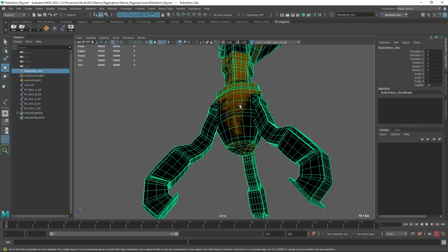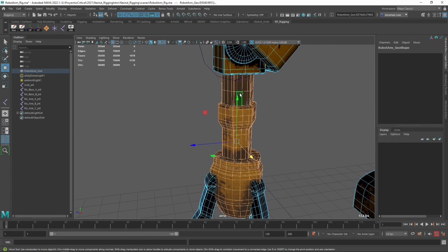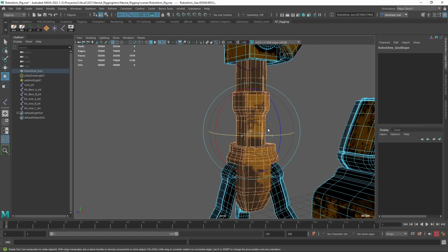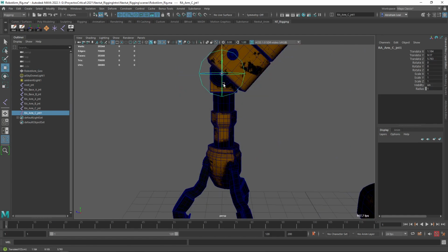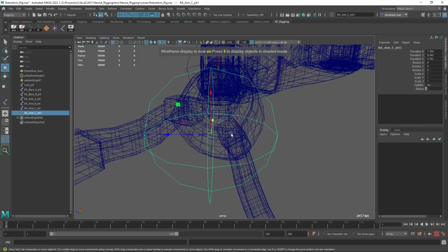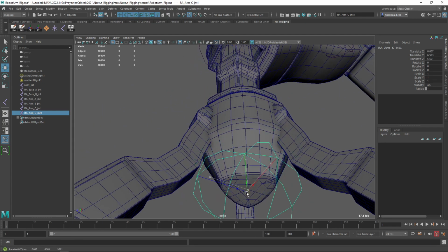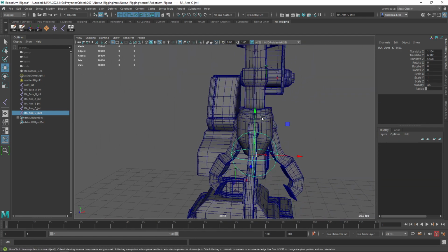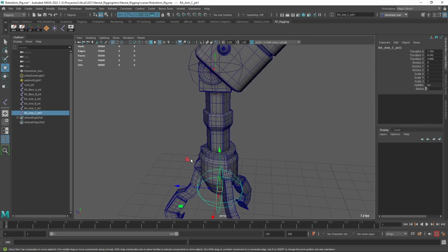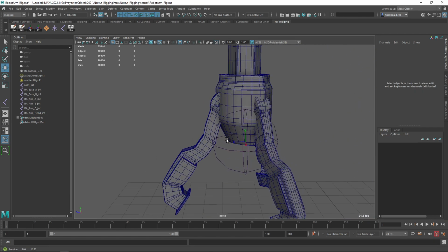Then we have this little head. So this face right here, and I thought about moving all of these elements. I want them to rotate on their own axis. So I'm gonna grab this guy, Control D, and I'm gonna position it. There's a vertex down here, that one right there. It's gonna be my pivot point, my rotation point. So when I rotate this thing, the whole little thing is gonna rotate as well. This I'm gonna call robot arm head joint. And now comes the interesting part.